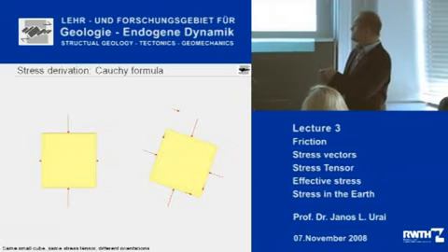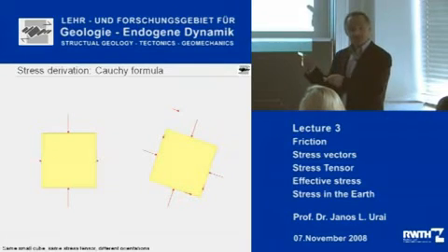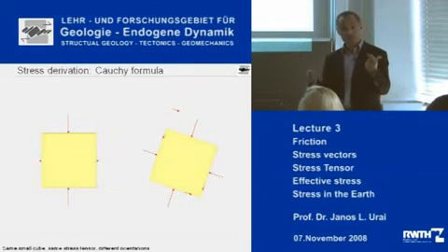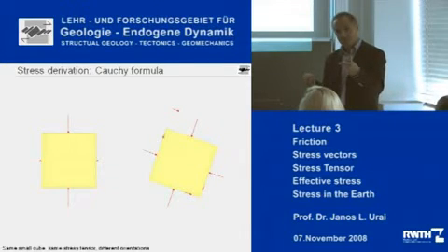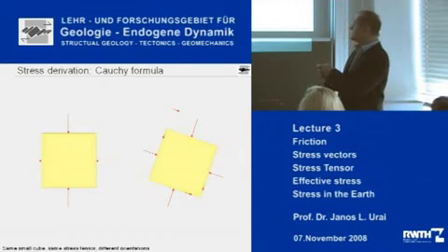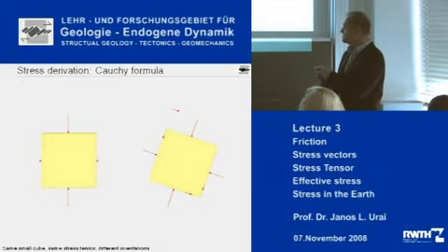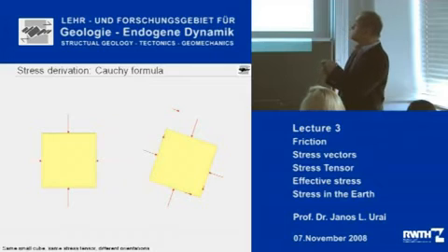And what we have learned is that there is this matrix that transforms the normal vector on the plane into the stress vector on that plane, and that all these stress vectors define an ellipse, which is really just a collection of the tails of these stress vectors for a given collection of values in this matrix.